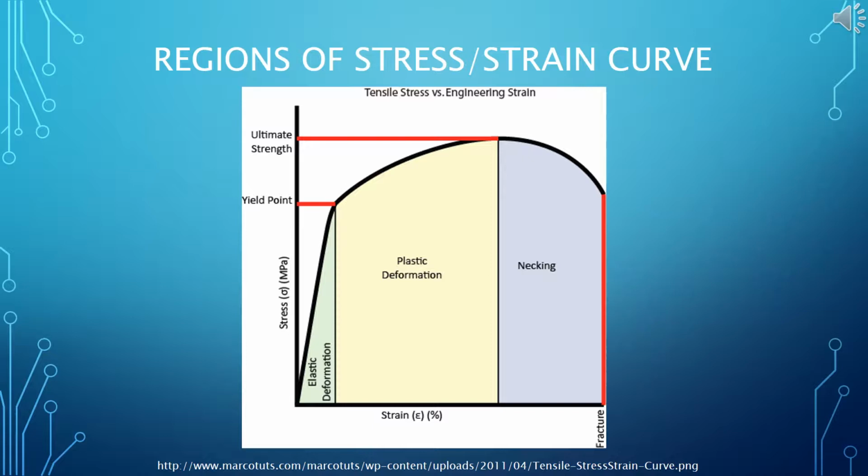In the plastic region, the bonds have permanently deformed and slip planes are activated. If the force is released while the strain is within the plastic region, the sample will not return to its original length. Instead, it will return to a strain connected to the point in the plastic region with a line having the same slope as the Young's modulus line. Lastly, after the sample has reached its ultimate strength, it begins to neck, meaning that the gauge diameter is noticeably less than the original diameter.